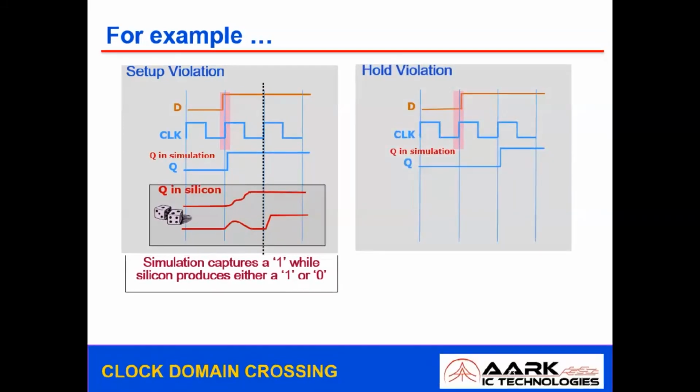Now, look at it the other way: even post clock edge, if your data is changing, before the clock edge the data is stable, so it has the setup window, and post clock edge it has violated the hold. When it violates the hold, even in this case, the simulator doesn't figure it out. The only thing is that in the next clock edge you'll get the stable data. Because the data changed post clock edge, the flop cannot capture this particular data. If the data is stable, it might capture at the next stage, because it has stable data before the edge of the clock as well as post edge of the clock. Therefore there are no setup and hold violations, so you will not get metastability.